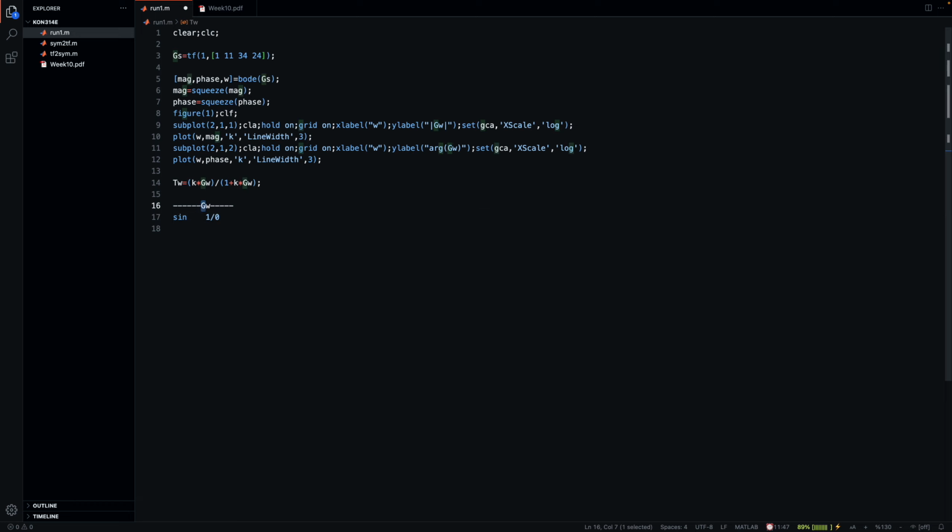Then, and this should be basically the closed loop, this might tend to infinity. If we have a division by 0, then naturally the amplitude becomes infinity, and therefore the signal should be multiplied with that, which should also tend to infinity, which we call instability.